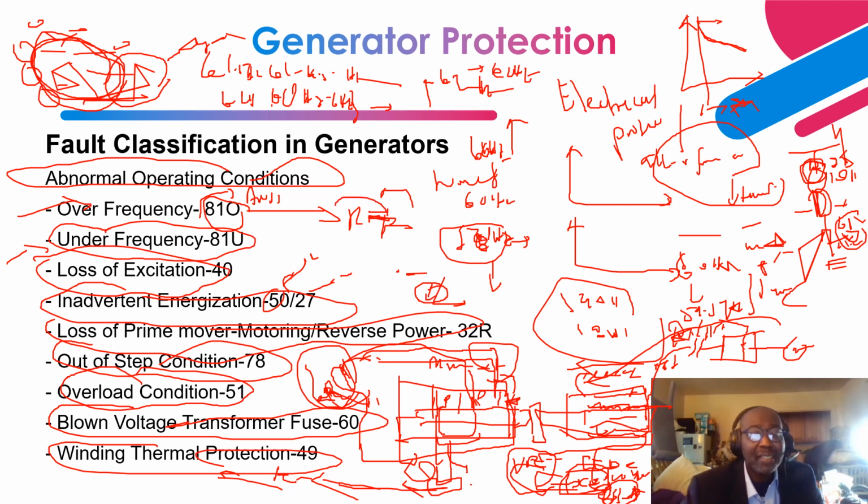So what this RTD element does is it measures the resistance due to the heating, the build-up of heat in the winding. Right? So if for whatever reason there should be a short circuit, basically it's going to cause heating, right, and a change in resistance, and that can result in heat buildup. And so that's how this protection element protects the generator.